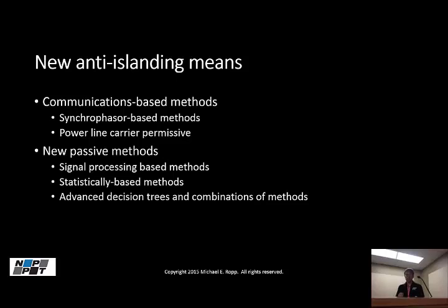What you need, more than anything, is a continuous carrier. As long as there's always a power line carrier signal there, we can use the presence or absence of that carrier signal to tell me when I'm still connected to the substation. So this method is extremely effective. It works very well. And you remember I mentioned that you can have more than one switch in the circuit. If I put a signal generator in the substation, all the series switches on the circuit are all instrumented already. So there are some very nice things to recommend power line carrier. That, coupled with the fact that it's very intuitive, right? It makes a lot of sense, because the inverters are not going to reproduce the power line carrier signal. They may reproduce the 60 hertz, but they shouldn't reproduce the COM signal.